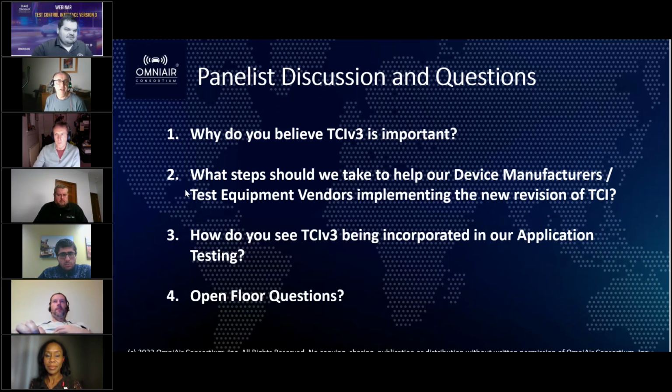I can start. Certainly, there's a reference XML configuration file that's been used for all the plugfests, at least, and that takes the definition out of J3161. I think it's a US specific 20 megahertz, whatever the safety channel is that's being used there. So yes, there will be different ones used throughout the world. From an OmniAir perspective, the radio frequency parameter settings probably won't change that much. So multiples could be shared.